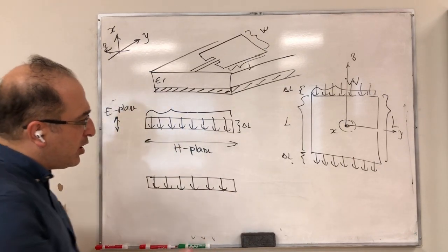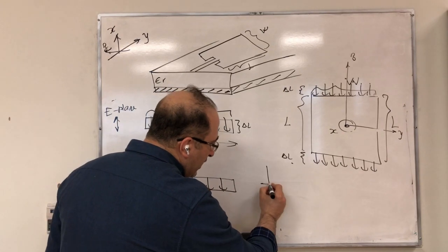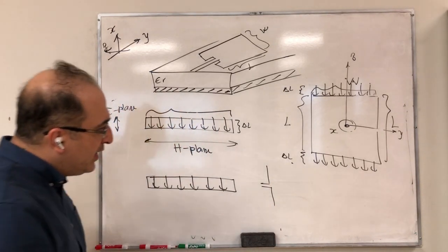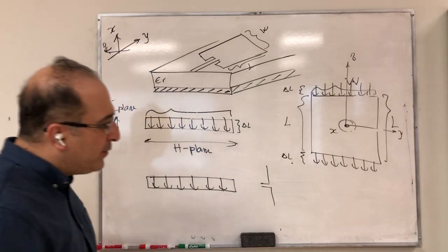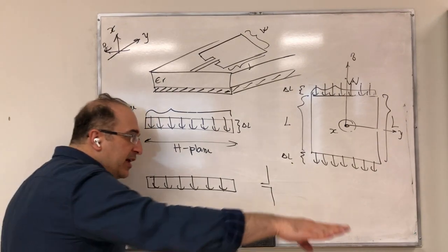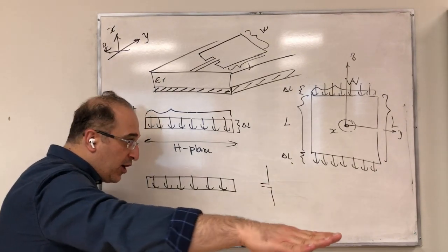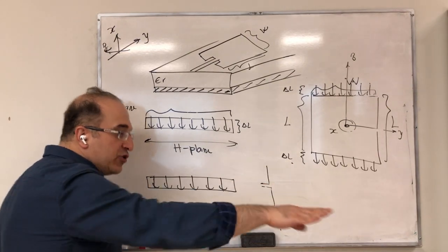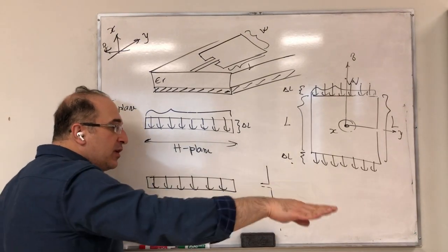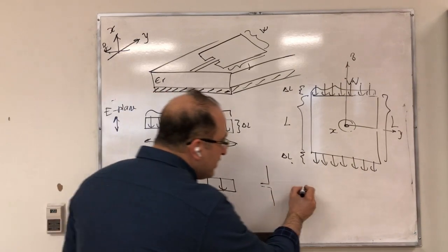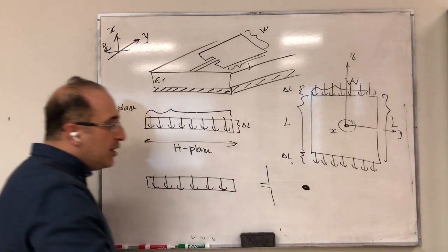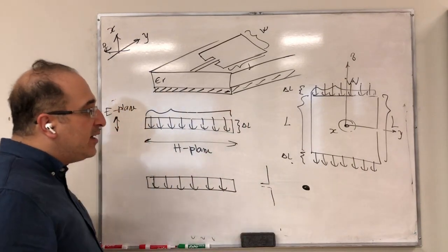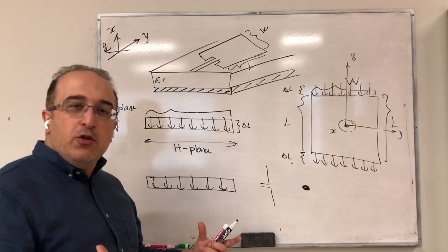And you could also connect it to the dipole antenna simply. If this is my dipole antenna, the H plane is perpendicular to the dipole. So if you make a cut of the dipole in the H plane, what you get is just a point, and a point radiates uniformly everywhere.